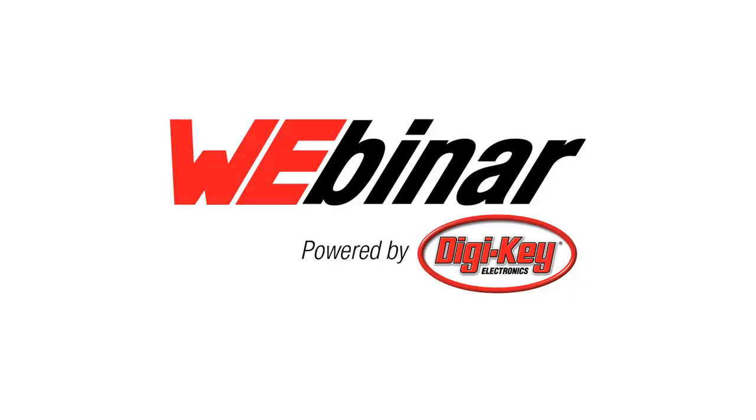If you look at the state machine that's implemented on those parts, and actually the spec as well, there is a decision tree whereby both ends will agree, okay, this is the highest power profile that we both support, let's use that. So more often than not, that is the application I've been involved with versus programmable power supply, where it's changing on the fly. Not that you can't do that, certainly, and that might be one of the applications where we use the I2C to change the configuration of the ST-USB 4500 on the fly. In that case, you might need an external microcontroller that could write to the memory and then force a renegotiation with the source side. That might be how PPS would be implemented with this particular device.